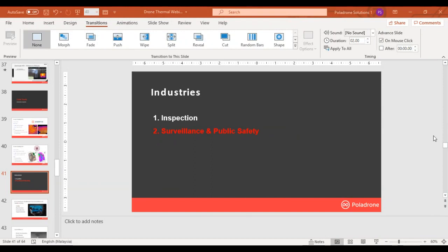According to that answer, the atmospheric condition will affect the thermal imaging, so it is generally recommended to take a series of images of the surface. The first is a variety of angles and how we take the pictures, and the second would be the time of the day. Yep, correct.